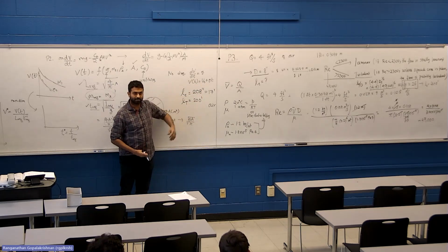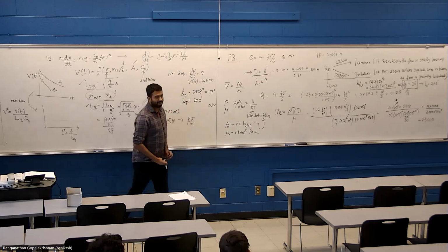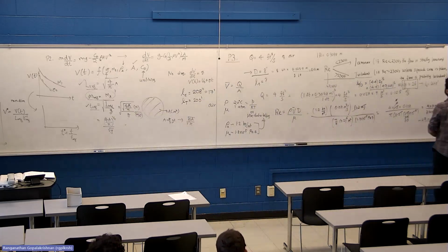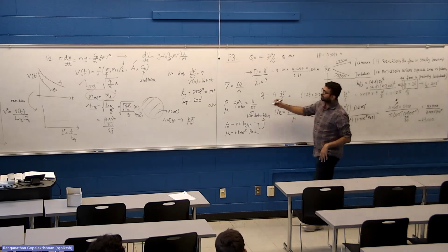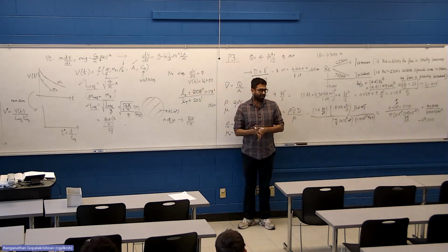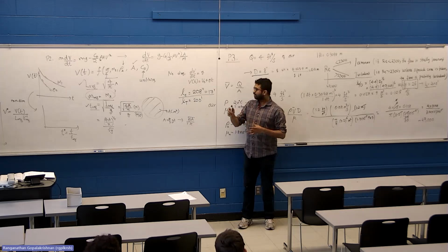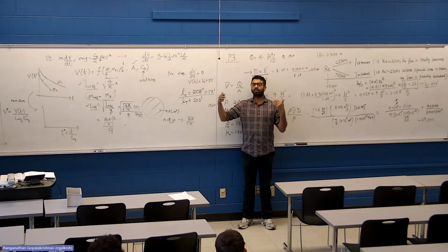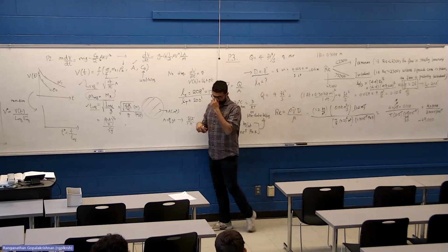So entrance length by itself, only in this course, only in this exam, somebody will just ask you to calculate it to see if you remember the formula. But in real practice, entrance length is usually an intermediate step in a bigger picture analysis, where you are trying to see whether it's significant or insignificant compared to the total length of pipe that you are trying to analyze. Okay.